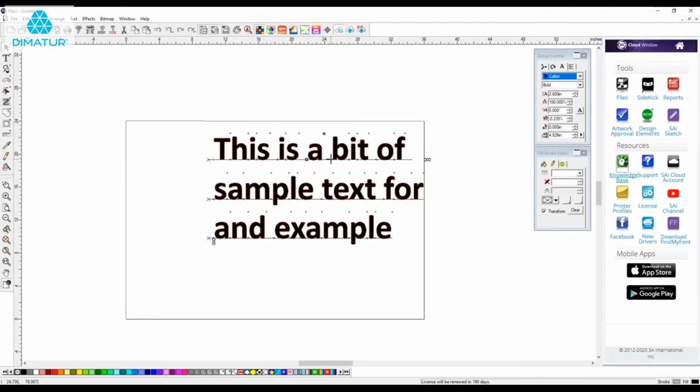And the black boxes allow me to change tracking or spacing of an object based on that letter. So everything ahead of the B is going to move along with it. Now the great thing here is if I hold Control, I can edit each line individually. So I selected this letter and I'm holding down Control. It allows me to move that one individually in a horizontal fashion. But if I hold down Shift, it allows me to go up and down with this letter. So really flexible in terms of what you can do. This text tool is really awesome and allows us to do all kinds of customizing.